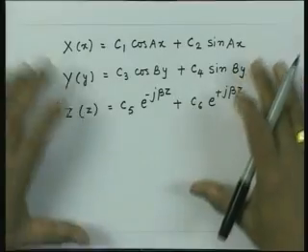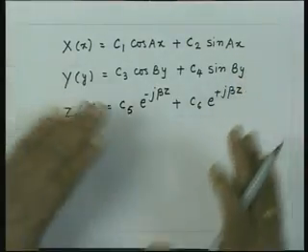So, while writing these solutions, first we use our understanding which you have developed with the parallel plane waveguide, that is, in the transverse direction between the two conducting boundaries, we must have a standing wave kind of solution, and along the length of the pipe in which the energy is going to propagate, we have a travelling wave kind of solution.